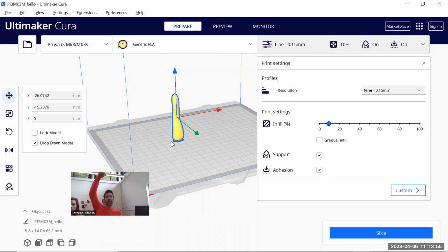No? This is an example. I wouldn't do the opposite because then it goes with the trunk, a lot of support to hold the 3D printing of the top. So I would always think twice about how to organize the piece so it doesn't have support. Now, if you really need support, you have it.